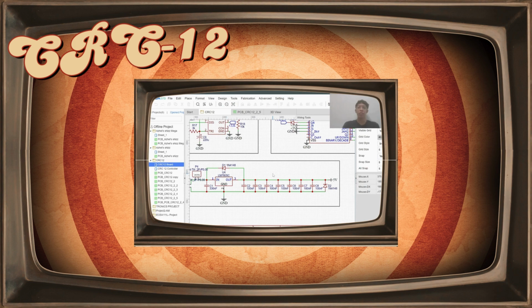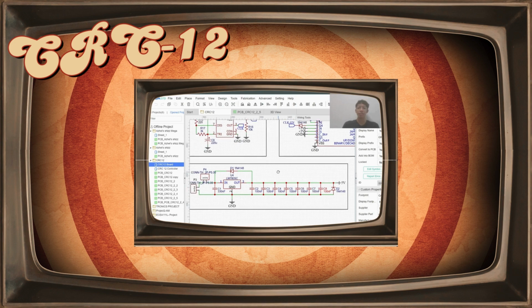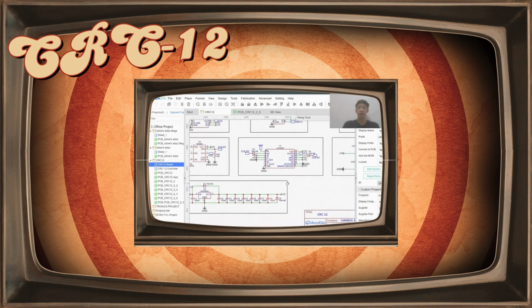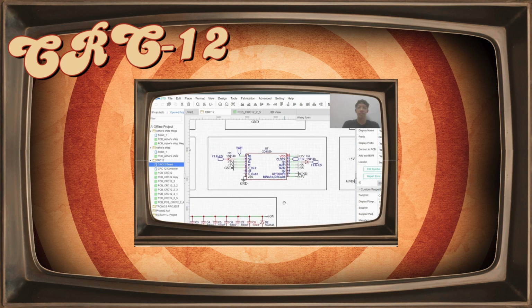So whenever we apply the wrong polarity in our circuit, they will protect every single IC, since they will immediately short the reverse polarity. And then we also have these decoupling capacitors, which will be placed near every IC. So that's a few changes for our 5-volt regulator.